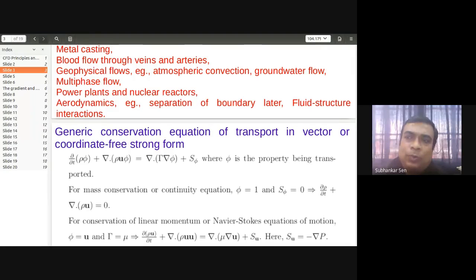If we talk about fluid dynamics, these are the cases where you have the exact solutions of the momentum equations. Momentum equations are also known as the Navier-Stokes equations. So when the advective terms or the convective terms become zero, it means that the fluid will have no acceleration, or the fluid is moving at a uniform speed.